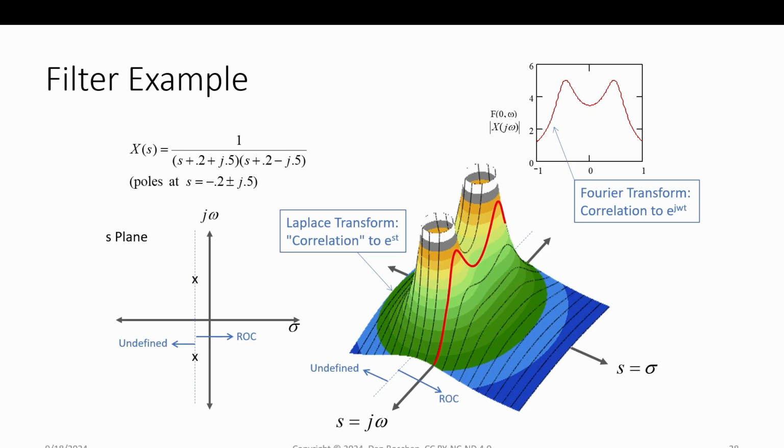So this is a second-order low-pass filter. If you plotted it on a log scale, dB and log frequency, it would look like a traditional low-pass filter you might have seen with some slight peaking, coming down 40 dB per decade as it's dropping. That is what you're seeing here, given by the two poles, given by the denominator. If you multiplied it out, it's s squared, so it's second order.